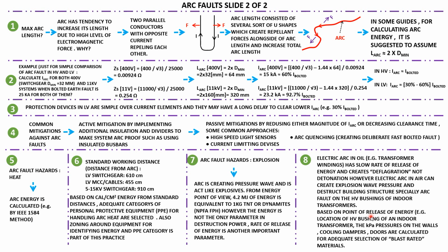forces on the building. So basically what electrical engineers should do is give the maximum expected release of energy at any point where they expect to have an arc, and give that energy to the fire engineer. They model that with some sort of equivalent TNT.